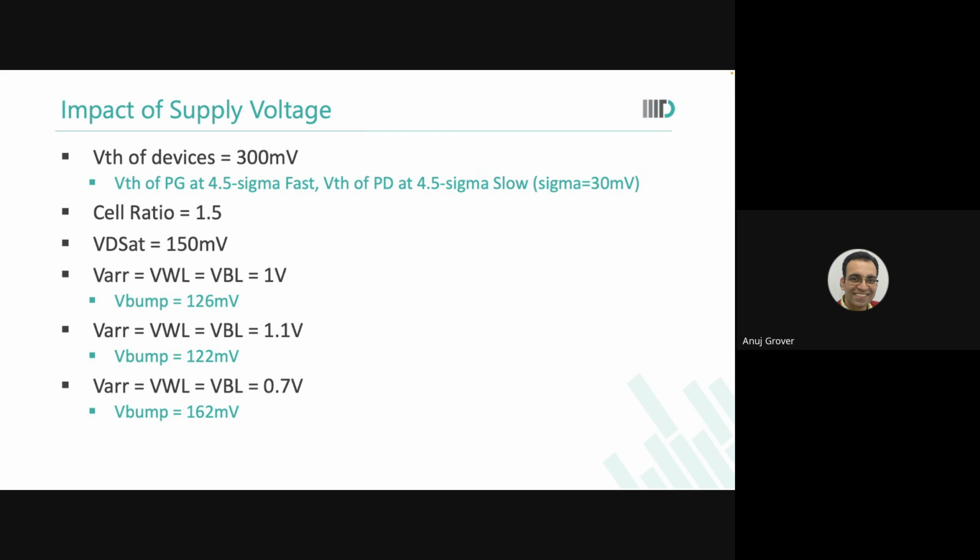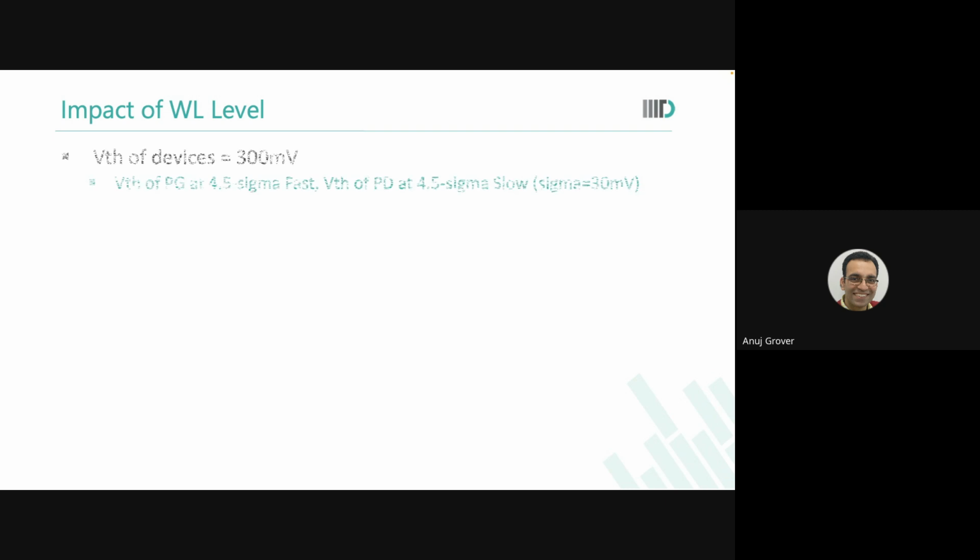It is a comparison between the subthreshold strength of the PMOS and the subthreshold strength of the NMOS. The trip point may change because of the mobility changes, whatever, but it will still work. But a memory cell is not a CMOS logic that we're talking about. It's an analog circuit. So at low voltages, it goes for a toss, both writability and readability. So what do we need to do? We need to put in place what we call assist schemes.